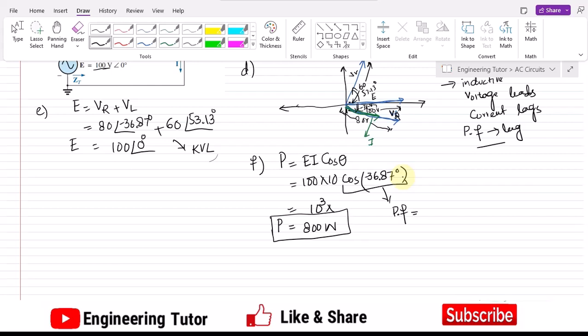So what is basically the power factor? Power factor is the cos theta, or you can also see that power factor is the value of the real resistance out of the total impedance. Okay, so the ratio of the resistance with the total impedance is basically the power factor, and you may calculate it from this one. So in order to find the average power, you have to multiply with it the power factor as well, which shows you how much resistive element is already available in our total impedance. Okay, so that is part F.